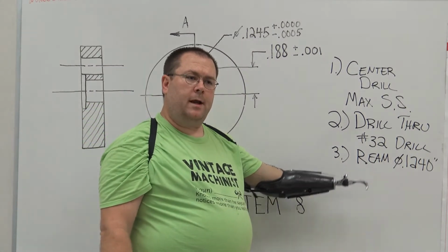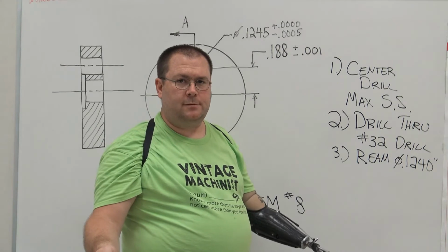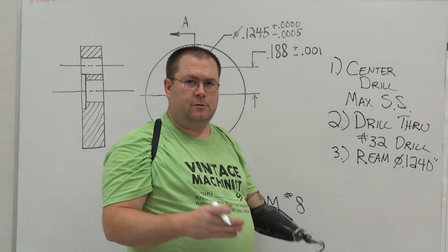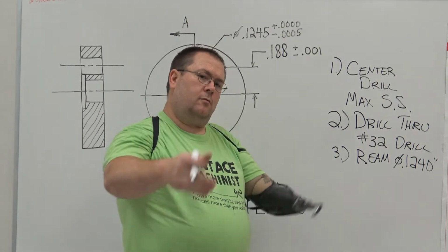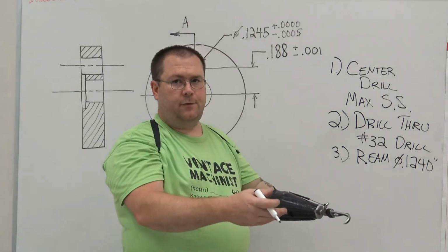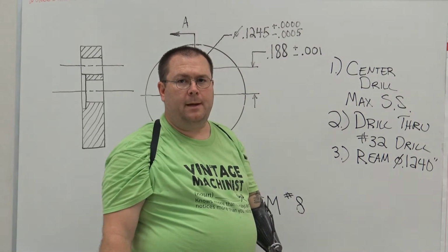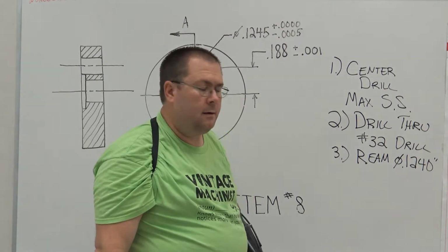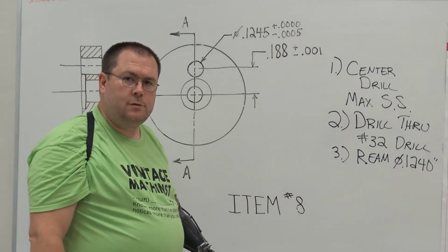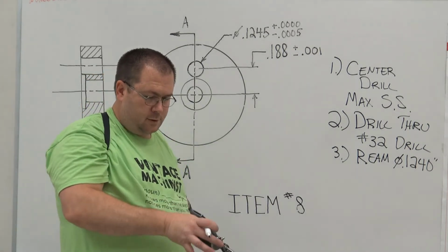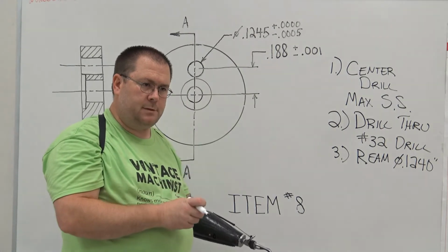On a 6-flute reamer, that's 3 times as many flutes as a drill bit. Chatter starts becoming a real problem, so I want to reduce the RPM. If I had 6 flutes, I'd like to reduce the RPM by a factor of 3. Well, these reamers are small enough that they only put 4 flutes on them, and those 4 flutes constrain it well enough to give me a good precision hole.